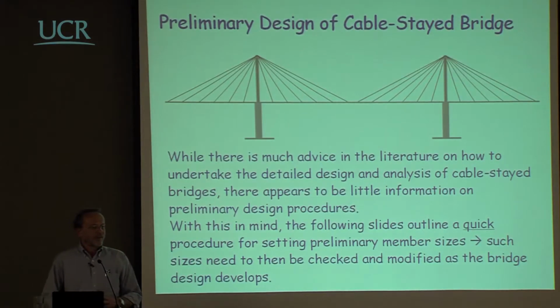So when you start with a cable-stayed bridge, of course you don't start from the seismic design of a cable-stayed bridge. You start from the global dimensioning, and of course you start with gravity, because after all the bridge has also to cope with gravity. And if you look at the literature, with the exception of a recent paper that I published 2 months ago on this subject, there is a lot of material about analysis, about how to deal with resonance of cables and so on, but it's very unusual to find some indication on how to design a bridge.